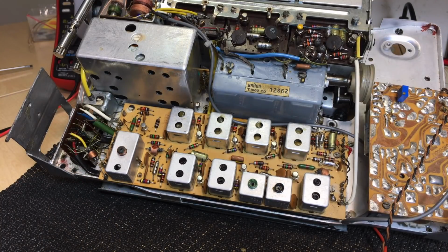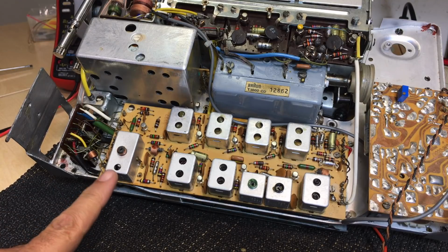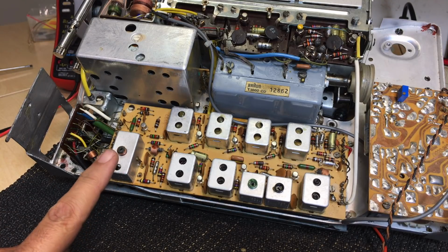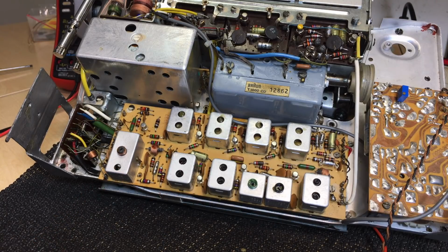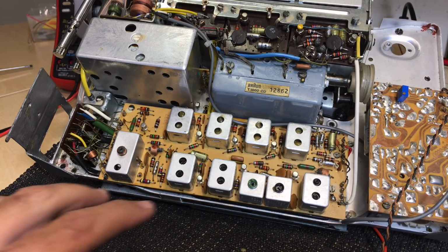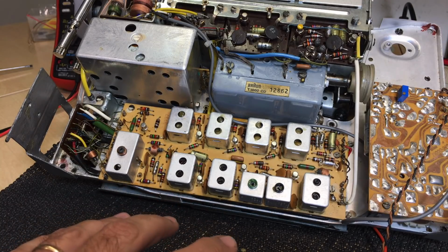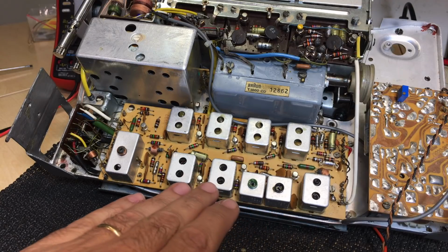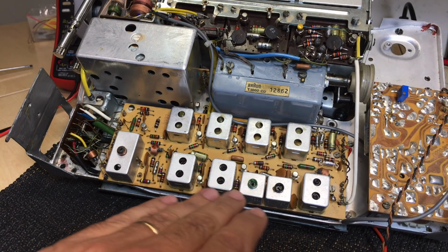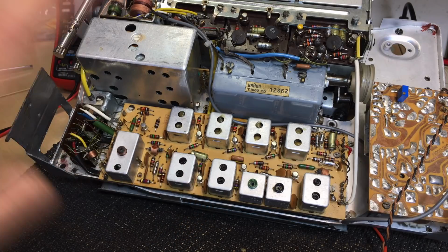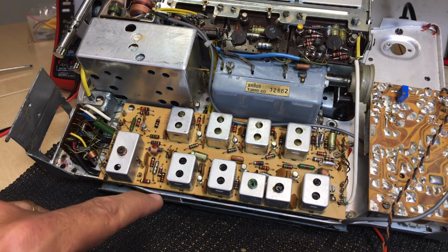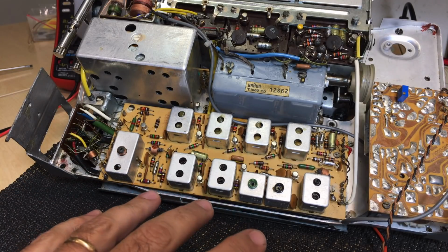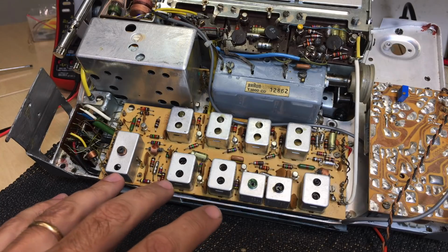Now why do you do that? Well, if you want to pick up single sideband amateur radio transmissions, you need to provide your own carrier. And the carrier is precisely at the IF frequency, which should be if this thing's aligned properly. So what happens is normally you've got AM radio, it's got a carrier which is modulated with the audio on there, and it goes through there, and this thing follows it through, carries it through with the IF frequency, and then gets rid of the IF frequency and just leaves you with the modulated audio. With single sideband, they sort of give it to you without the carrier. They give you the information, but no carrier.